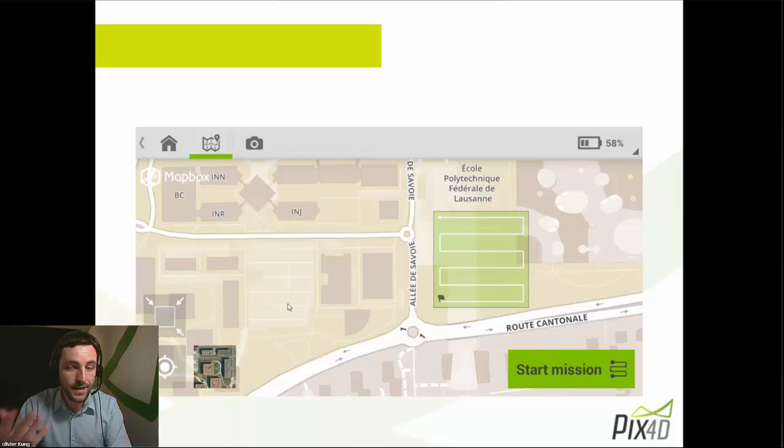To get access to the satellite data background, you need to be connected to the internet. So what we suggest for now is to not connect to the drone first. Open the application, and this will load the map. Only after that, connect to the drone using the Start Mission button. So let's pretend that we are still connected to the internet. Then you have the second button here, which allows you, of course, to center the map to the location of where the phone is. Once you click it, it's going to center it.